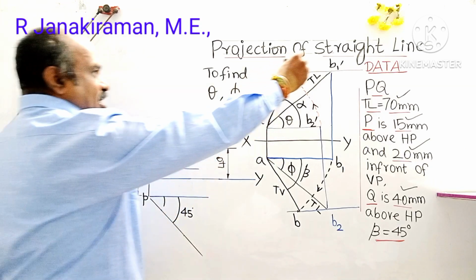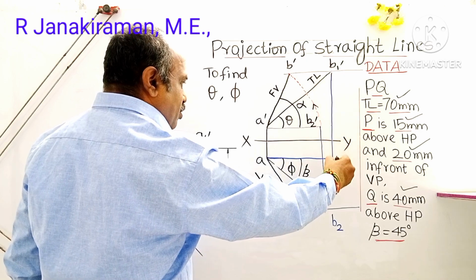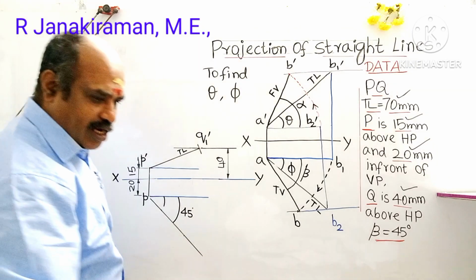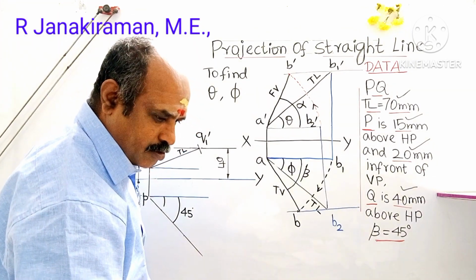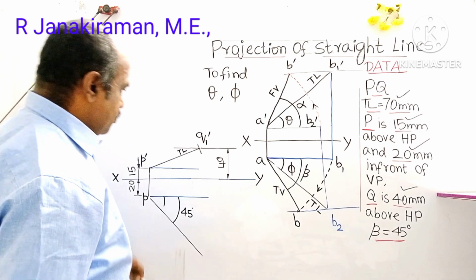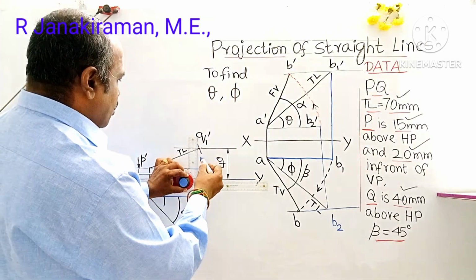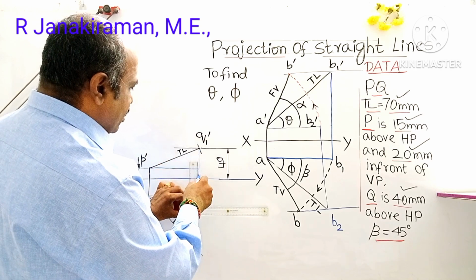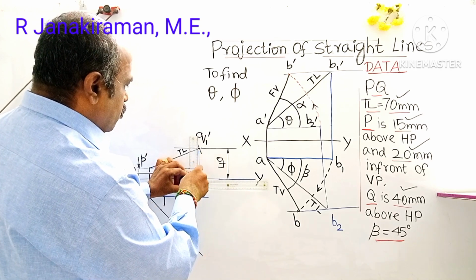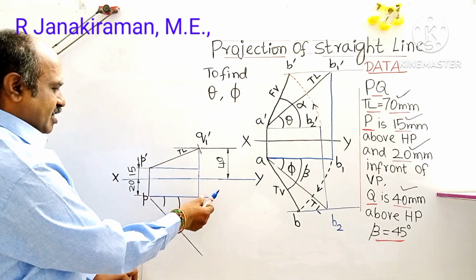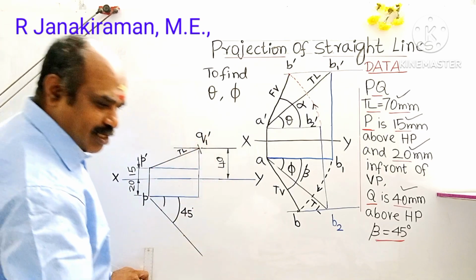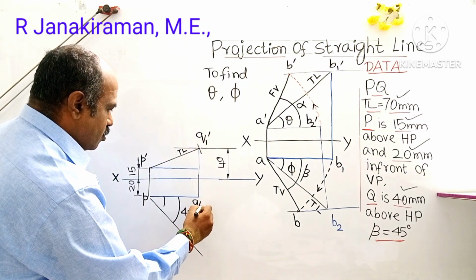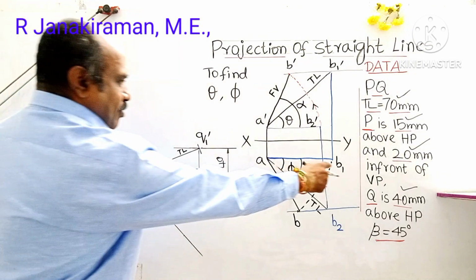Okay, so from B1 dash, draw a vertical projector downward. It's a projection line. So this is our B1 dash. Instead of B1, here it is written as Q1 dash. Draw a vertical projector from Q1 dash downward. Where it intersects with this horizontal locus line passing through P, this point of intersection shall be marked as Q1. Q1 dash means the letter Q2 is to be provided. So similarly Q suffix 1. Okay, so next, this is the point.